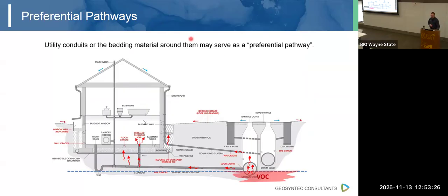So typically you want to have that U-bend, that P-trap of a water gap so that you aren't getting sewer gases coming back into your house. But if you have a floor drain that's dried out, if you have that one sink in the basement that nobody uses, then you might be getting these vapors coming in from this and just bypassing the subsoil gas entirely.